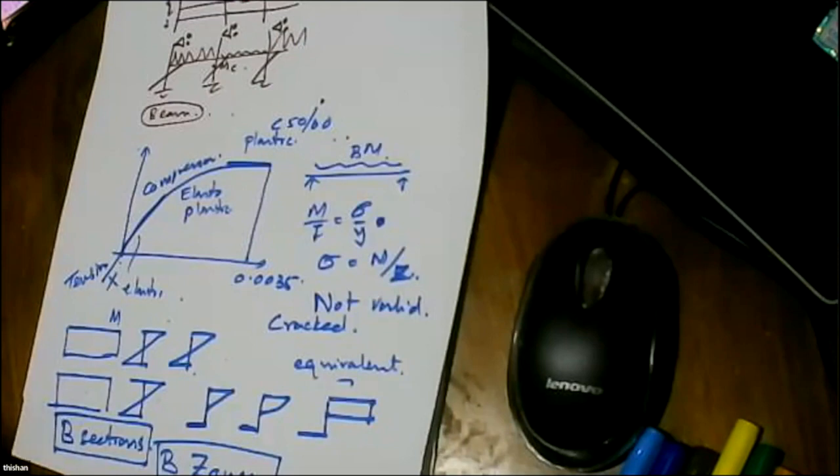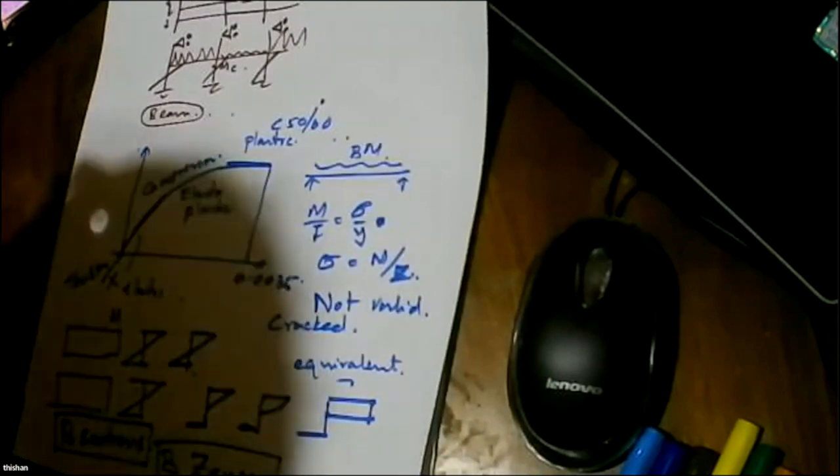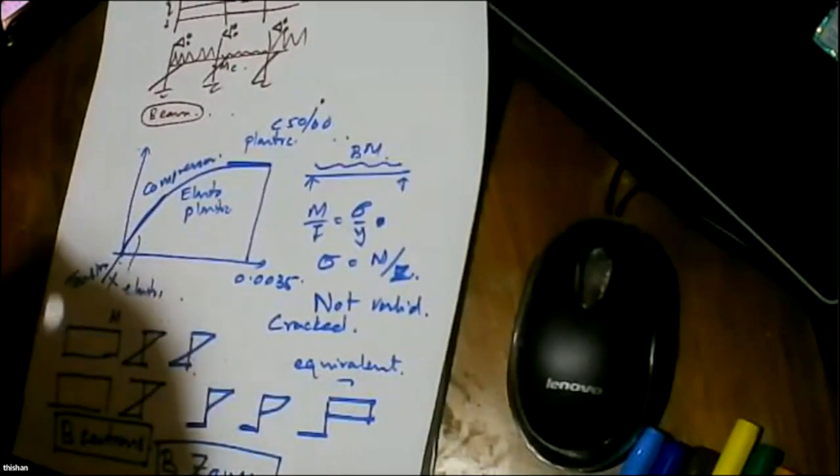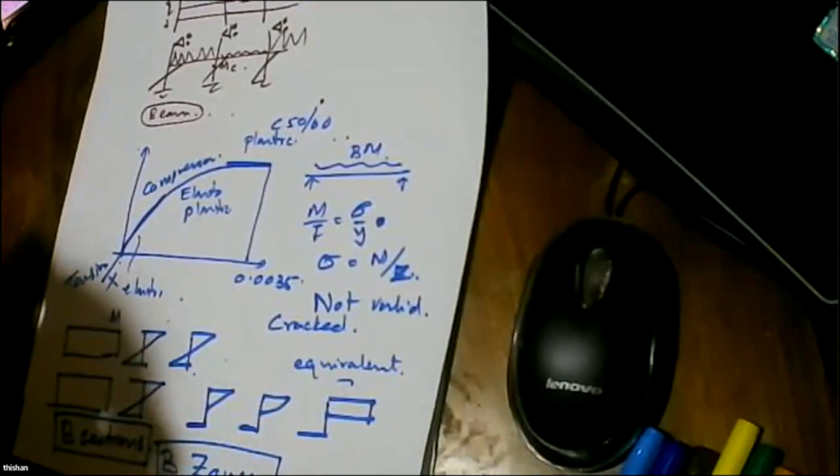The moment you develop bond, it can be as high as 400 or 600 kilonewtons per meter square under service conditions. If you are going to get that type of very high value as the skin friction, and if we socket long, even though the rock is fractured vertically, the confinement is very high and we will not have any problem.